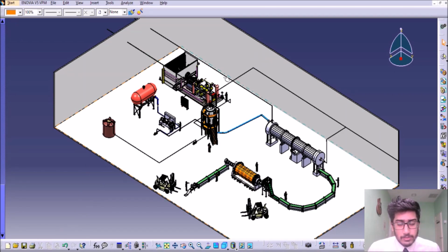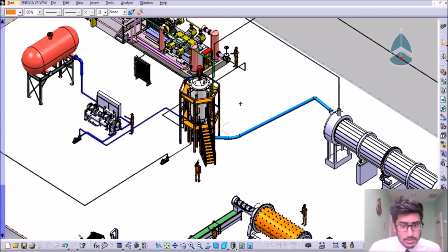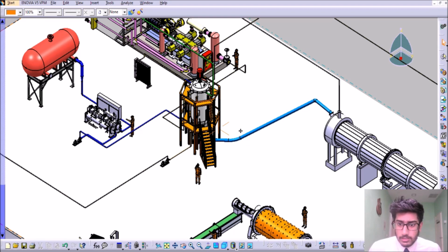The first equipment we have over here is the nitrogen gas generator. This nitrogen gas generator is a huge machine by itself, which generates the nitrogen gas, and also has a booster system, so we don't need a compressor. It then pumps nitrogen gas into this piping, which sends it to the pressure vessel. Then this over here is the air compressor, which compresses air and sends it to the pressure vessel as well.